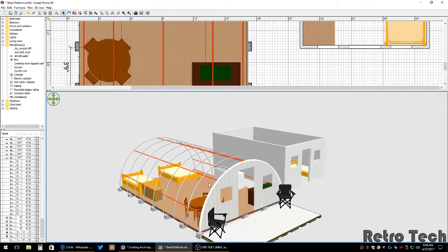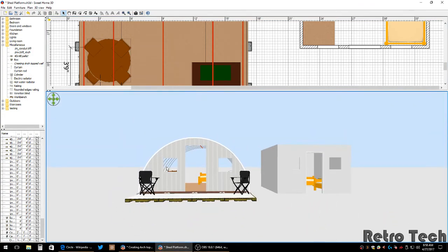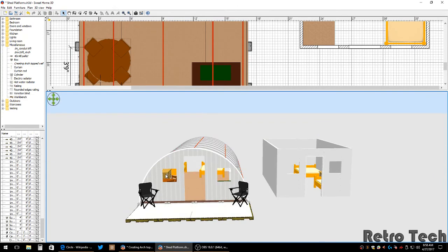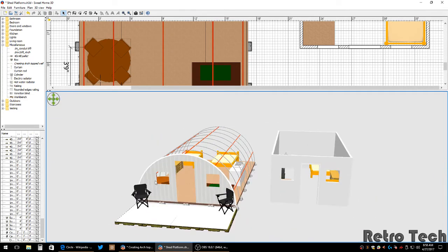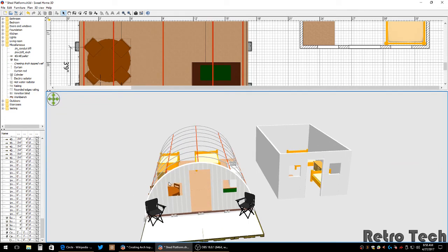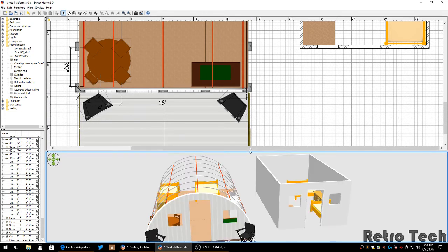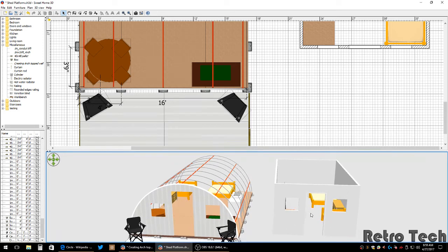Now, when we look at our 3D representation, I now have a solid, curved, arch-topped wall. Now, for the windows and the door framing, I can come back using the box tool, and I can create a myriad of options to make it look like a casing around that door just using the box option in the software. So that's it. That's how you're going to do that.